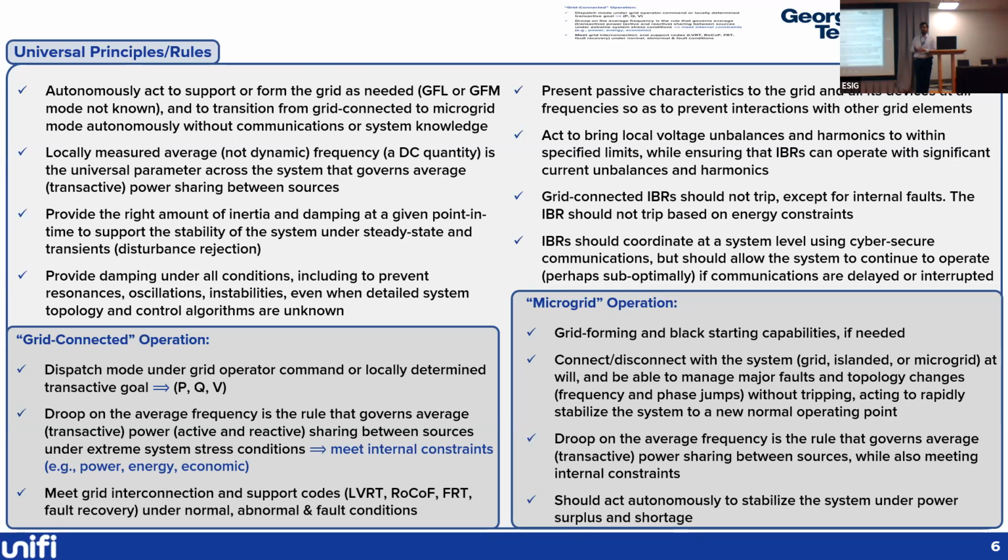Now, what this might also mean is that we explicitly don't want to prescribe any mode switching. There are certain resources, certain inverters from certain manufacturers, which may look at switching modes. So they might operate in, say, a grid following mode and then switch to a grid forming mode if there is an islanding event that they detect, or if there is any other system operation that they detect. So what we want as an aspirational goal from the system side is that we don't want that mode switching to occur. If it does occur, there should be no visible indication of it occurring on the grid side, because we don't want a change in mode to really impact the system. So it should be a seamless transition if at all it occurs, but the aspirational goal is that it should not occur at all, which means that the way in which the grid forming inverter operates, both in the grid connected mode and in an isolated mode, should pretty much be the same in terms of the types of services that it provides.